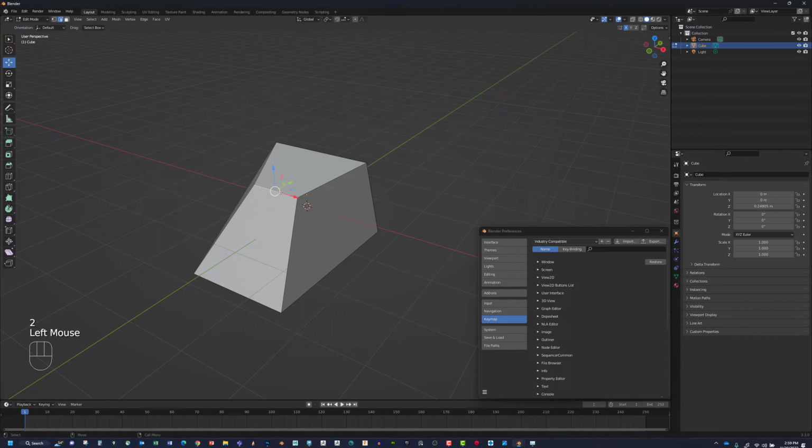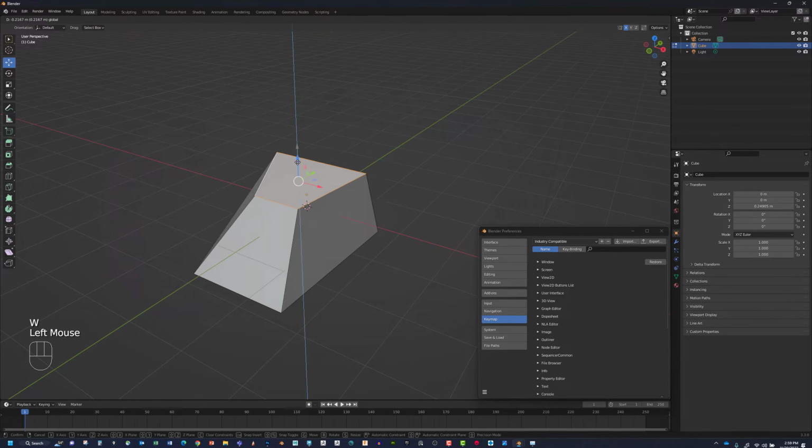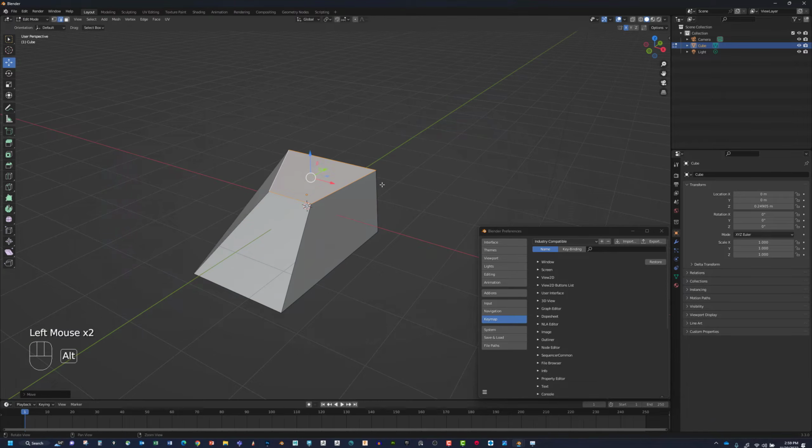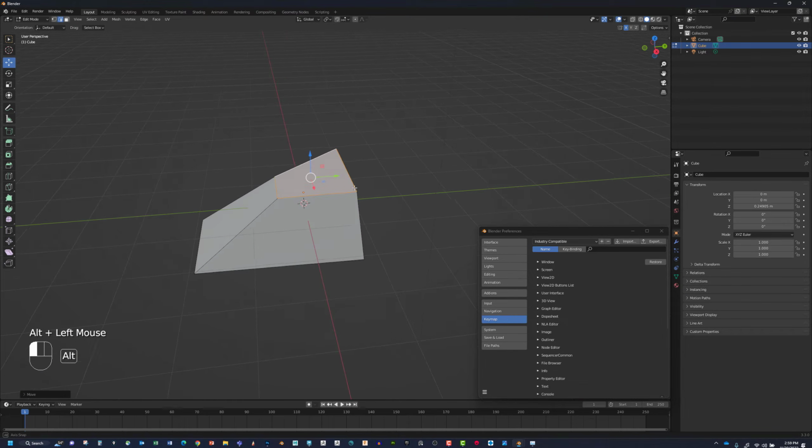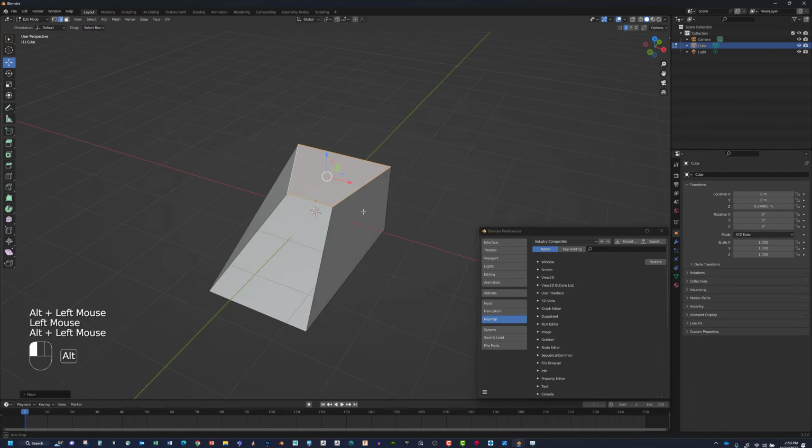I'm going to select 2 and then select an edge here, and you can see in the industry compatible mode it's going to be real easy for us to use what we looked at. If we're going to do the pick tool, we can tap Q, so if the manipulators get in our way, we can do that, and we can just select multiple things like this and then tap W for move. And so maybe I move these faces down and maybe I want to move them back at an angle like this. So you can see that, and I'll just push this back a little bit further.